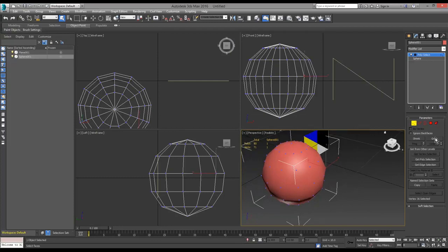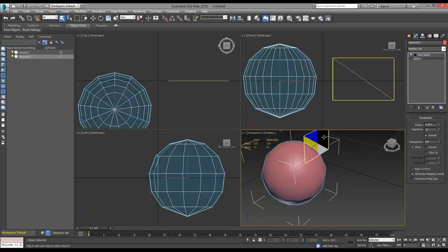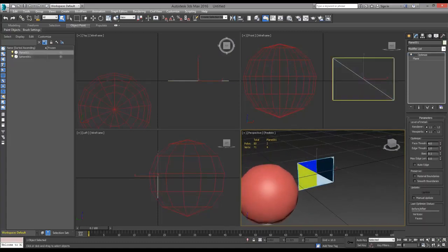So sometimes you hear about the vertex count, sometimes you hear about the poly count. It depends on your object whether it's twice the number or not. So for example in here, when we look at the plane here, you see that I have 1, 2, 3, 4 vertices and 1, 2 polygons, because each face is separated into triangles.